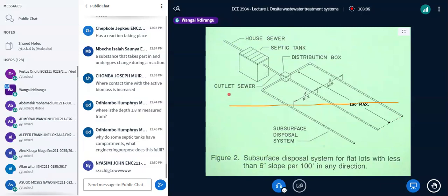If you think of it, you're having a trench there, and you're having a pipe coming down this way, and then releasing the water through perforations. Okay, if you take this to be the pipe, and this is a trench. So as you go down here, there's a very high likelihood that by the time the water gets here to 25 meters, 20 meters, all of it has been taken out, so that this place remains permanently dry. So to encourage distribution, you limit this to about 30 meters, okay?